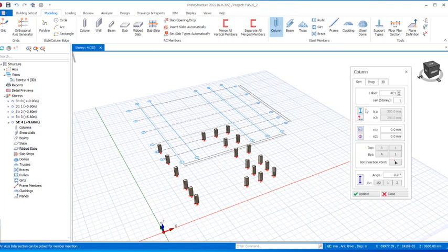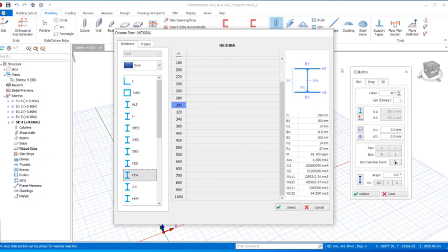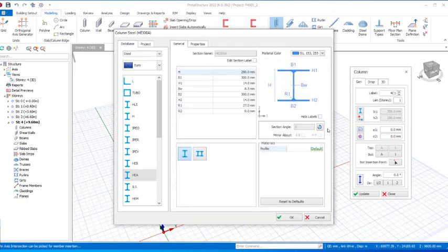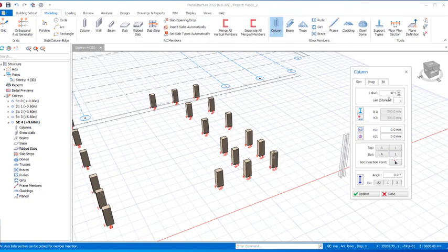So we have this time around. Let's click on this and make sure that we selected the right sections, which is that, and then select and rotate it this way. After which click on the OK options. We really want this column to get to the foundation level, so what we need to do here is key in 3 instead of 4 in the provisions.